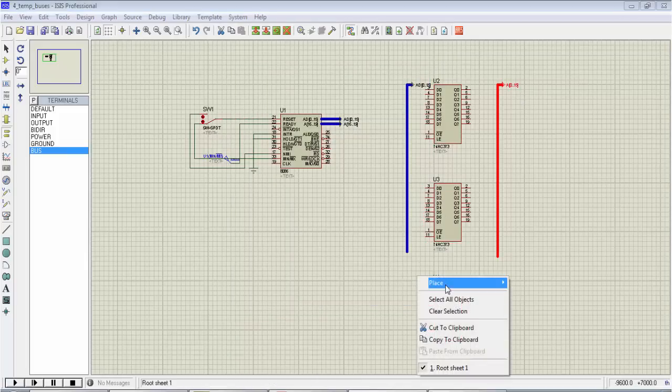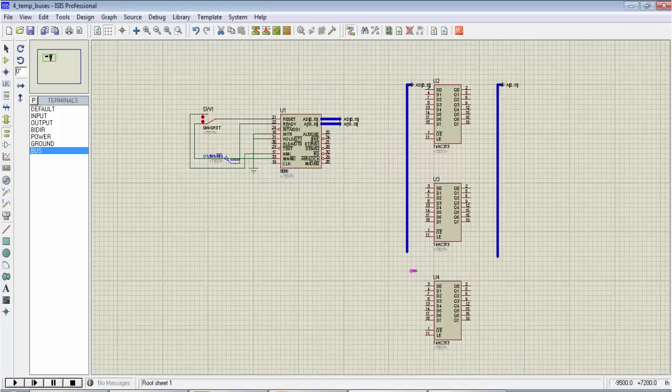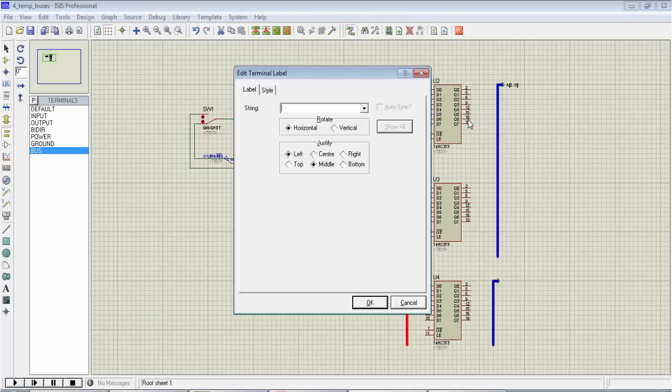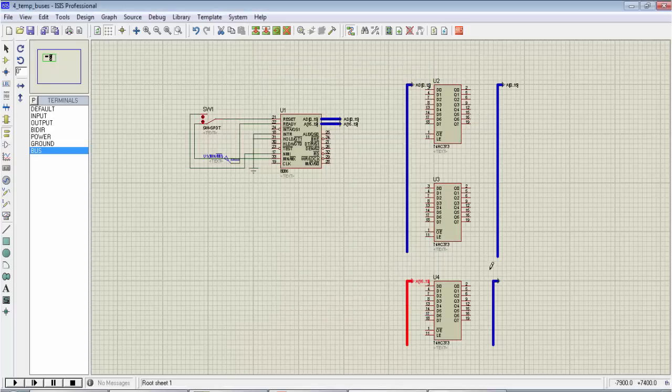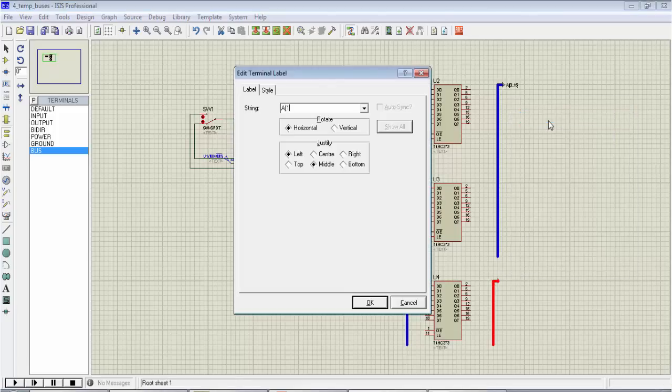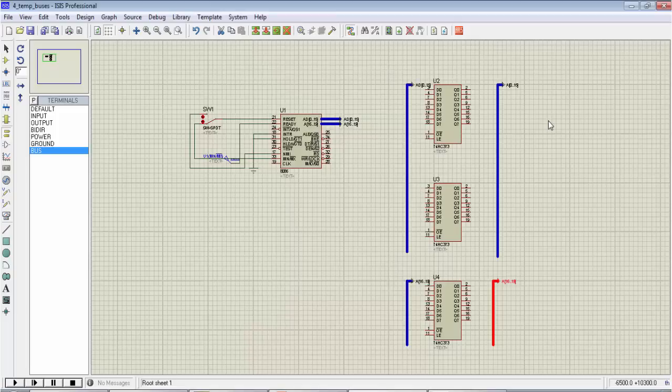Accordingly, we'll add bus terminal for the third latch: terminal, bus, input bus, output bus, again mirror image, X mirror. So I'll draw the bus. Right, so the label for the input bus for the third D-latch is going to be A 16 to 19, since it's multiplexed with some other signals, and the output is going to be A 16 to 19. Right, so I've got input buses and also drawn the output buses.